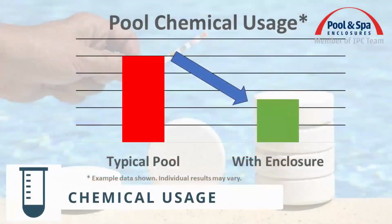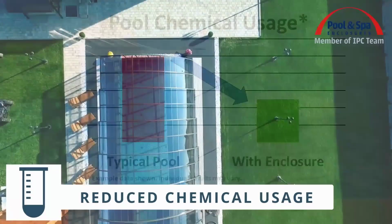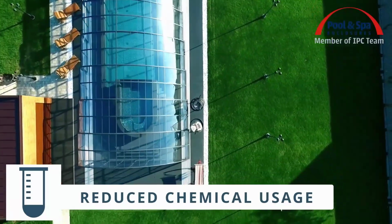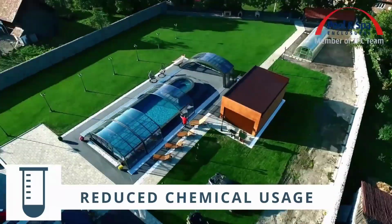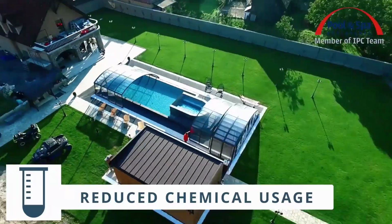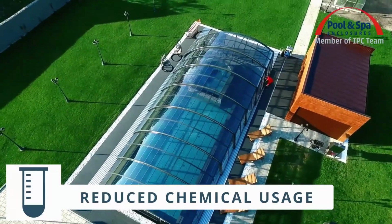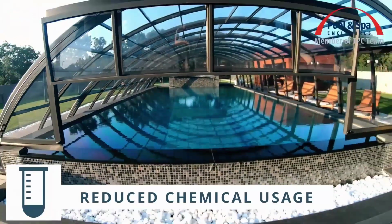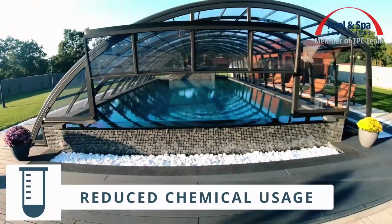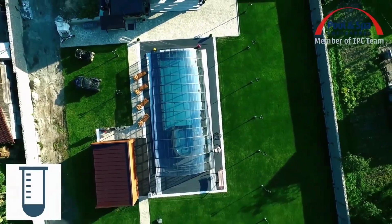Speaking of cost savings, an enclosure will significantly reduce the amount of chemicals needed to properly balance your water. By keeping leaves and debris, acid rain, and other unwanted intrusions out, the need for chemicals is drastically reduced. When the ultraviolet rays of the sun hit your pool, chlorine is released as gas into the atmosphere. Amazingly, you can experience a 90% loss in chlorination in your pool on a bright sunny day in just a couple of hours. By reducing UV light, you reduce chlorine loss.